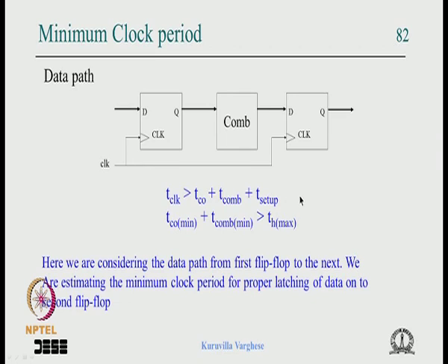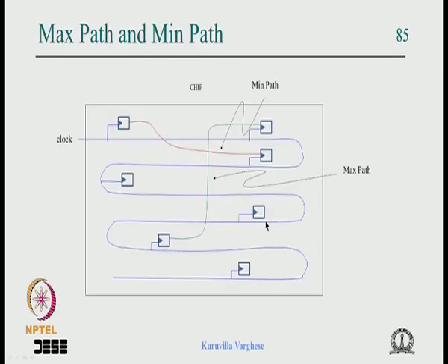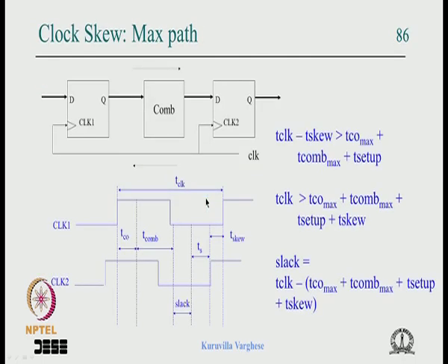So that should be taken into consideration when analyzing these expressions, and that is what we have done. We set two scenarios: where the clock and the data flow in the same direction, which is called a min path problem, and where the clock and the data flow in opposite directions. And we looked at the case where the clock and the data are in opposite directions.